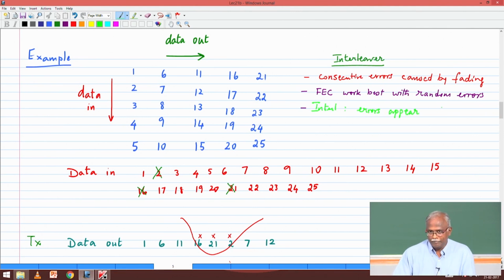Okay, we cannot change the fading, but as far as the decoder is concerned, it looks like some random errors, and the code might actually be effective. So errors appear random because of the presence of the interleaver and the deinterleaver on the other end. So what do we want to take away from here? Errors will occur as bursts in a fading channel. That is why coherent detection has its limitations, because if I have consecutive errors, then my likelihood of losing track of the channel is high, and once I lose track of the channel, I will have performance degradation in my errors.